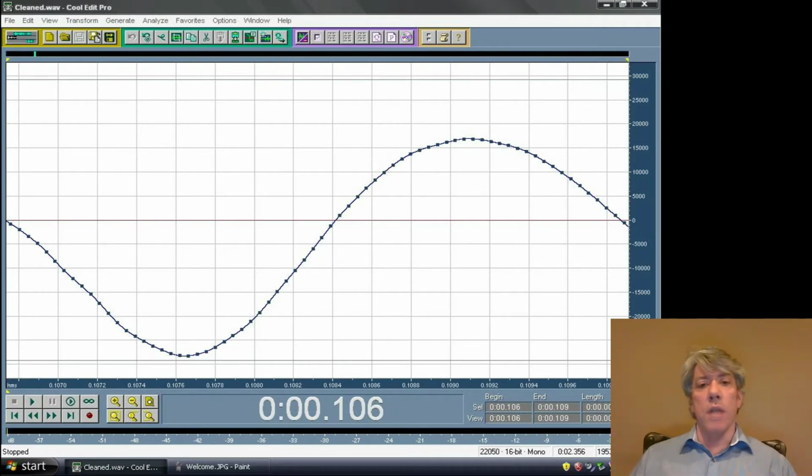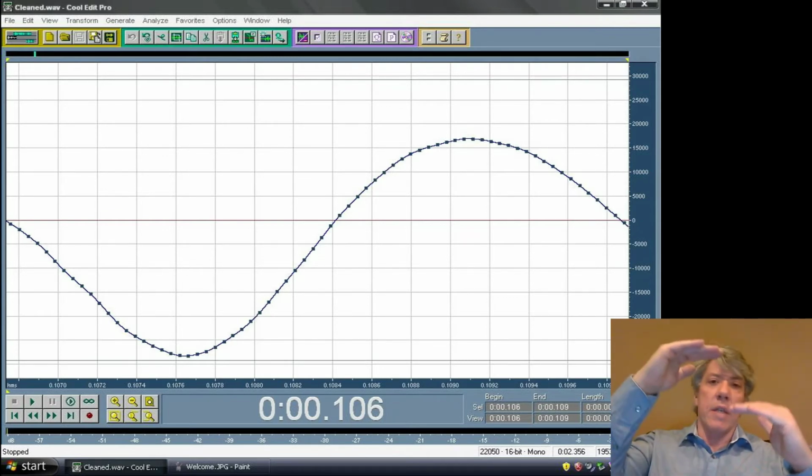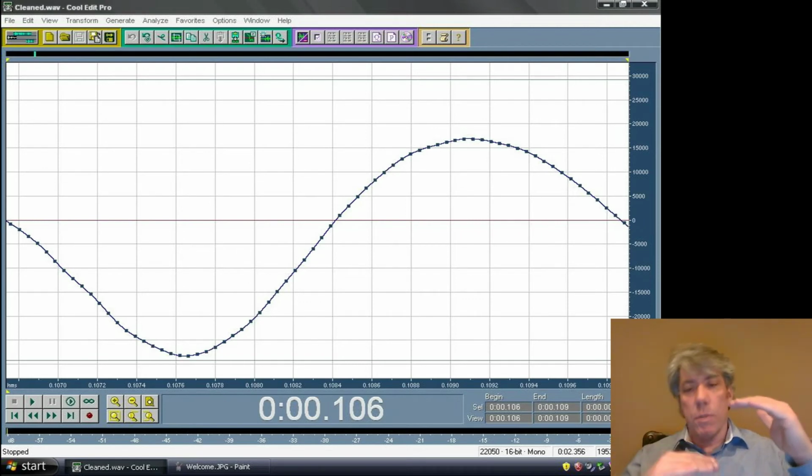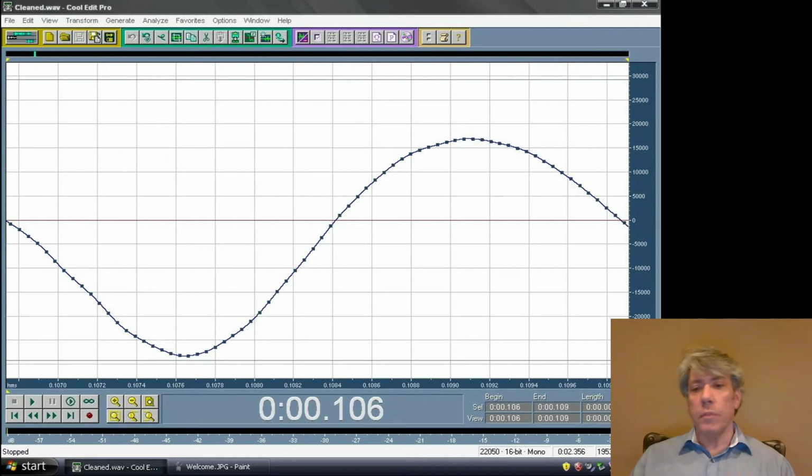And the way this worked is basically you think about it as very fine steps, from the speaker as low as it can go to as high as it can go. The lowest position being 0, the highest position being 65535. The middle position of the speaker, when the speaker is at rest and not moving at all, when it is quiet, would be a position halfway in between, about 32,768 or 32,767.